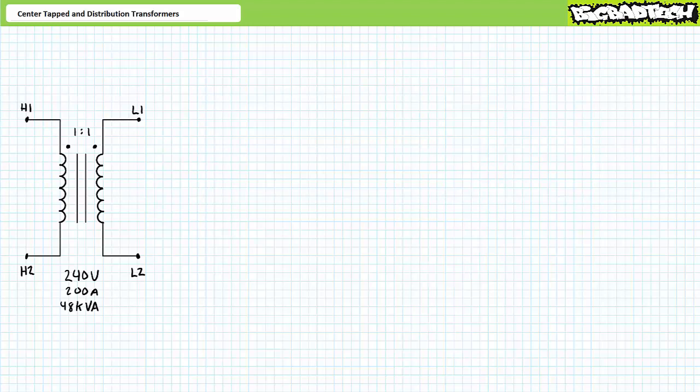contact. Isolation between the primary and secondary windings allows a degree of flexibility in the system, in that the primary side could be grounded and the secondary side could be ungrounded or floating, or vice versa. For now, let's assume both sides are floating without reference to ground.